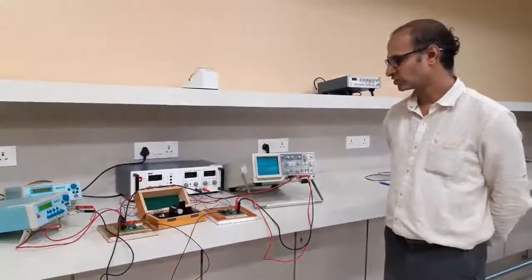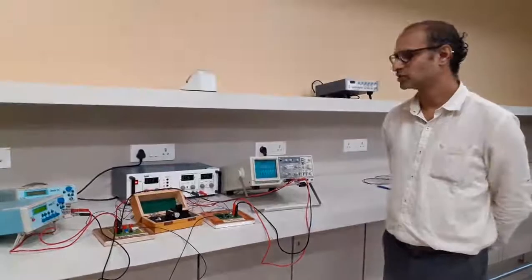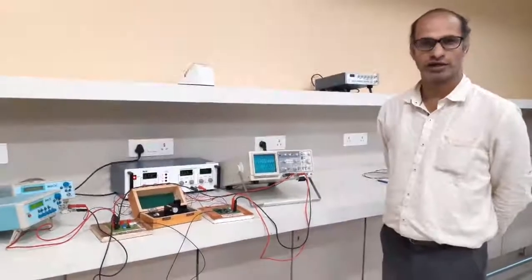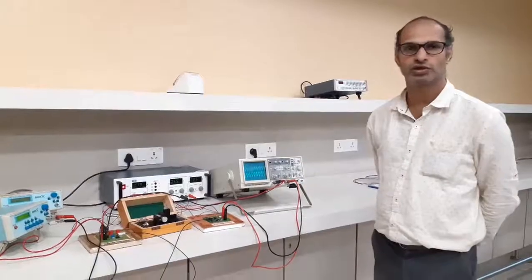Good morning. Today we will study the coupling losses when we connect two ends of the fiber. First type of loss is lateral displacement. Second type of loss is end gap displacement, and third type of loss is the angle between two ends of the fiber.